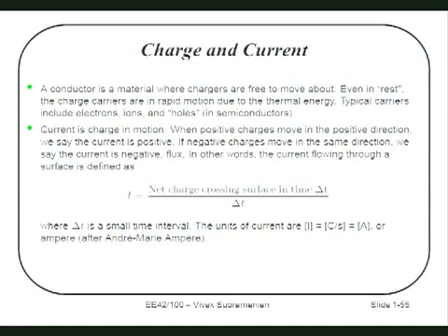But if I want to know I at 1 second, what is it? It's about 2 electrons per second. So you now see the difference between capital I and small i. Capital I represents essentially the non-varying part, which for a system that has variations tends to be the average. Small i represents the instantaneous part.